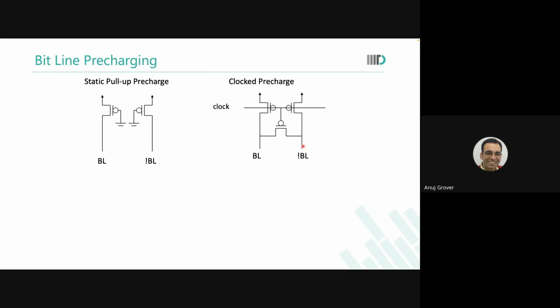The pre-charging happens after the cycle. Yes. In fact, in ROMs, you will see that, because, okay, look at it like this. In a ROM, there's no risk of loss of data. You also know that ROMs will not be used very frequently. Activity factor is still lower than what it is for SRAMs. So in ROMs, you do not pre-charge at the end of cycle. You actually pre-charge at the beginning of the cycle.